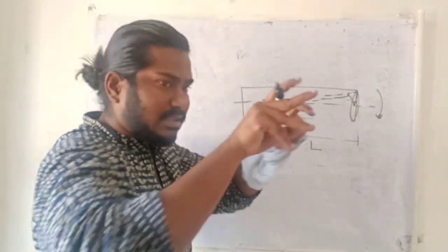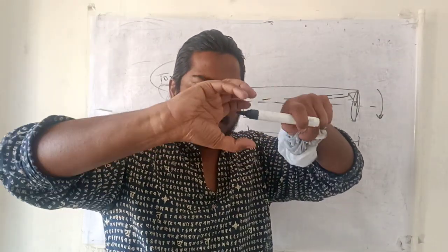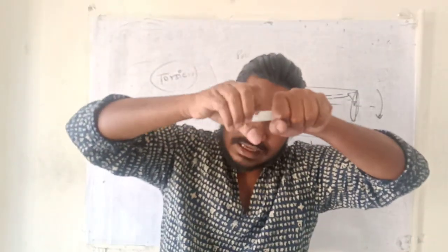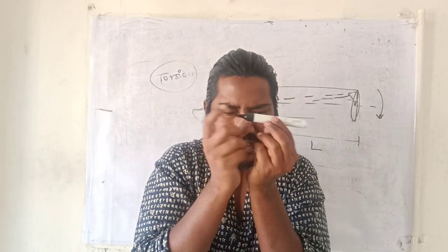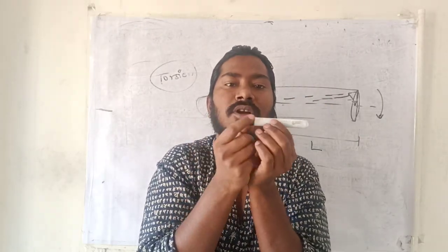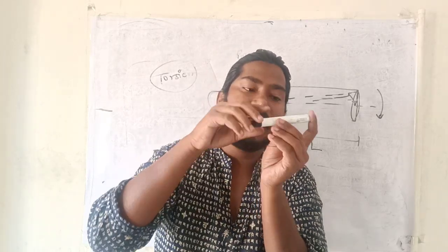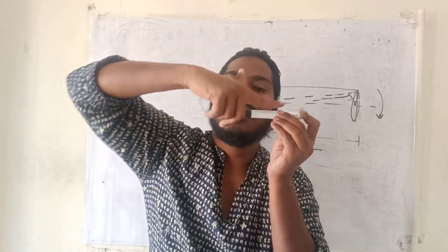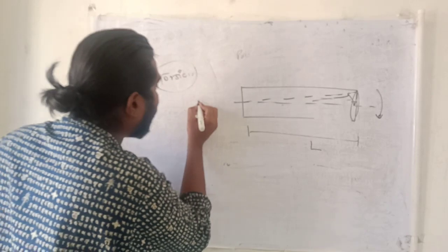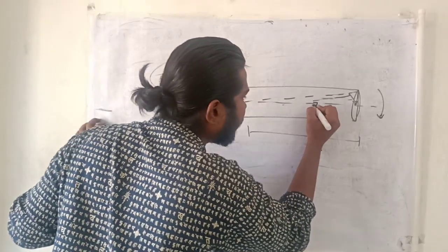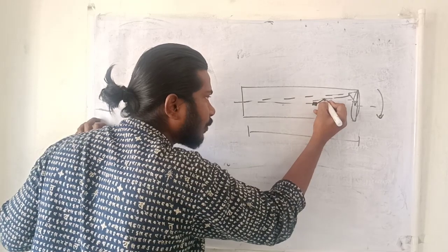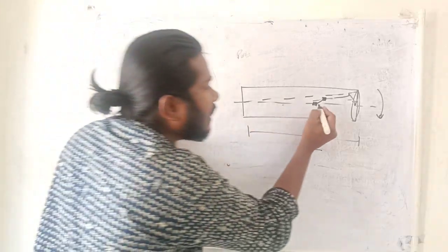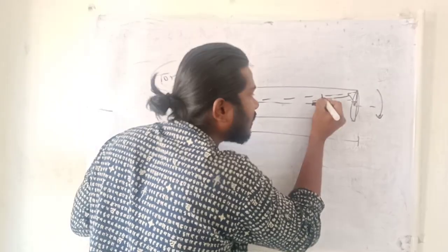Earlier, like this is a circular rod, there is a twist. I won't be able to draw it, I'm not very good at art. So if I'm providing the torque in this solid cylindrical shaft, from here, this is the reference, you can see the flex is occurring. Now an infinitesimally small component here will change its location somewhat to here, and it will change its location in an arc. This is the arc that is being created.